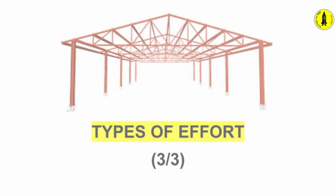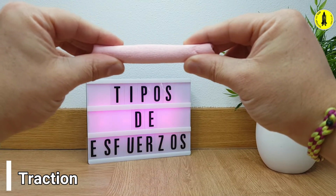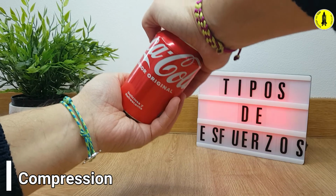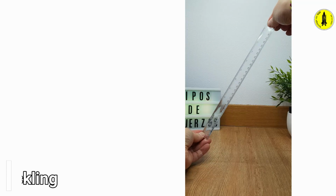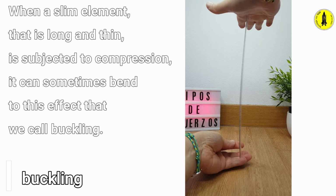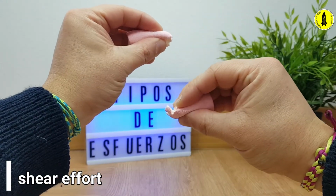Types of effort. Traction is caused by two opposing forces acting in the same direction and trying to lengthen the structural element. Compression is also produced by two opposing forces as well, but now we're trying to shorten the element. When a slim element, that is long and thin, is subjected to compression, it can sometimes bend, an effect that we call buckling.